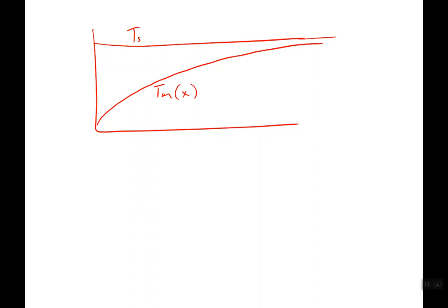If we wanted to look at just a small sliver of this pipe, we would look at this delta T. So in that small sliver of pipe, would it be a good approximation to assume that we can just use a regular delta T there? Delta T is constant. It would. And if it wasn't a good approximation, you can just make that sliver even smaller. So just in that little tiny space, we could apply Newton's law of cooling locally.